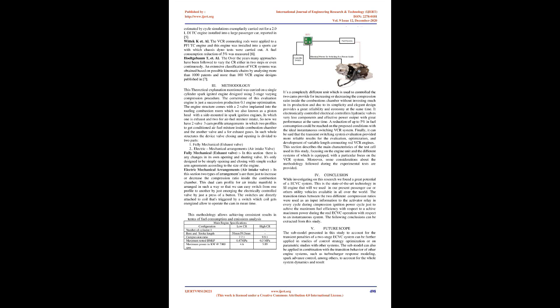Thus, to fully exploit the benefits of variable compression ratio at part load, it would be desirable to reduce the increase in pumping losses through VVT or lean burn. 2. Feng et al. It has also been shown that the increase in compression ratio increases the engine tolerance to EGR. 3. Shelby et al. Experimental results obtained from a V6 GTDI engine tested with different fixed geometry pistons and connecting rods to adjust different compression ratios are published in 4.